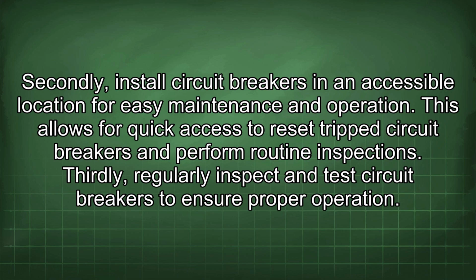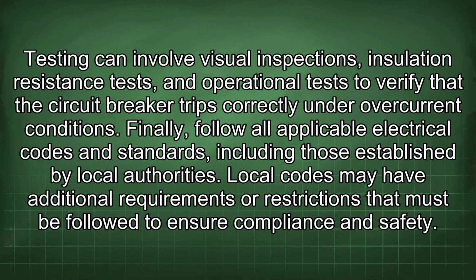Thirdly, regularly inspect and test circuit breakers to ensure proper operation. Testing can involve visual inspections, insulation resistance tests, and operational tests to verify that the circuit breaker trips correctly under overcurrent conditions. Finally, follow all applicable electrical codes and standards, including those established by local authorities. Local codes may have additional requirements or restrictions that must be followed to ensure compliance and safety.